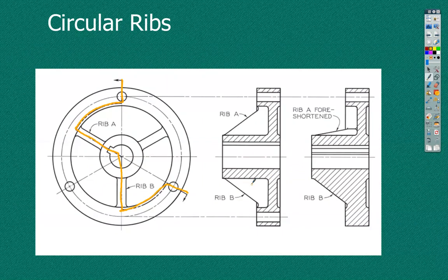Well, so when people are machining this, will shops ever be like, I want this certain view on there? Well, it makes it easier for them to see what's going on. Because if I just did a full section, this is what I'd get. And it really doesn't help. Here I can see this rib, but up here, this doesn't help me at all.